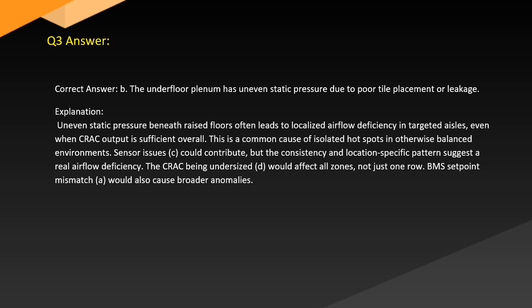Sensor issues (C) could contribute, but the consistency and location-specific patterns suggest airflow deficiency. The CRAC being undersized (D) would affect all zones, not just one row. A BMS setpoint mismatch (A) would also cause broader anomalies.